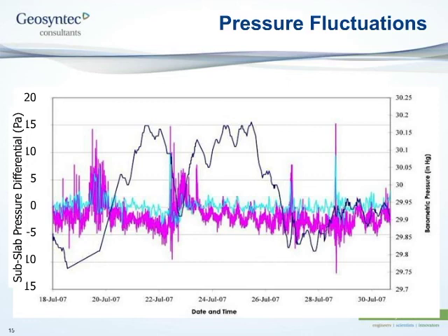They can sometimes average, like you see in the blue color, around a neutral value, and sometimes average around a slightly depressurized or pressurized value, depending on other factors such as temperature differences and mechanical fans that are either blowing in excess of air into the building or withdrawing in excess from the building.